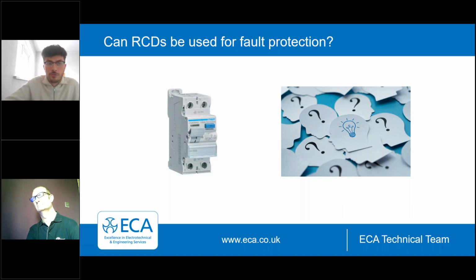Regulation 411.4.5 permits this. I think the most obvious example is where we have a TT earthing system. Impedance values are too high for overcurrent devices, so RCDs are employed, maybe for additional protection, but maybe for fault protection as well. So that's your typical example of where it's employed.